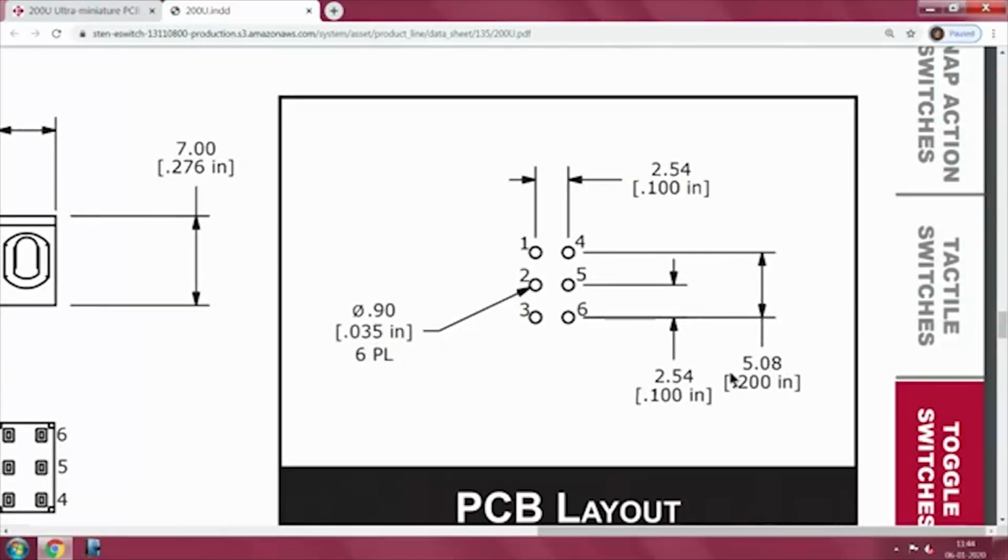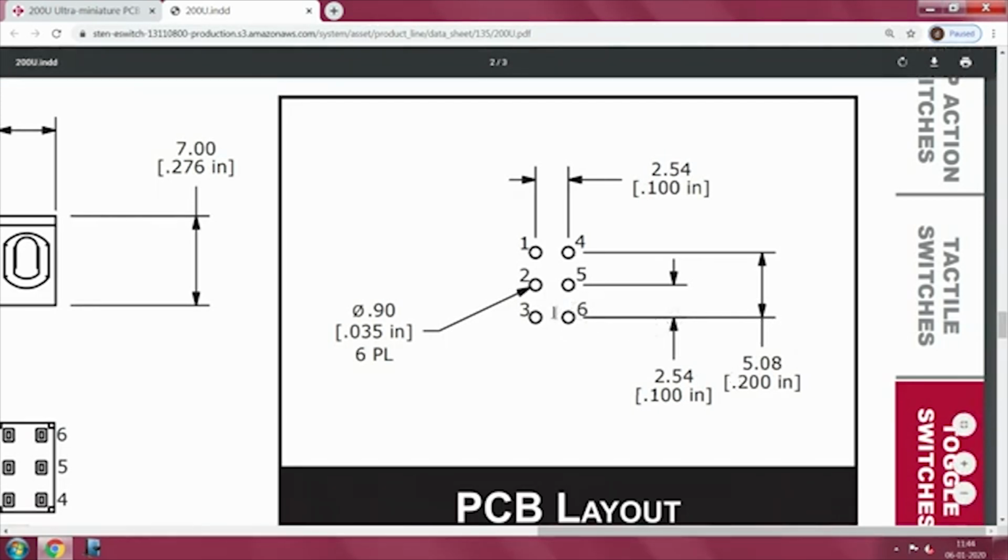So, especially if you are going to have a large number of components and all of them are going to be mounted on a printed wiring board, and that printed wiring board is likely to be laid out automatically, it is much better to look for devices which will give you this 0.1 inch which is given here. That is the reason why in spite of this thing I keep showing you this. You have seen this? Is a beautiful 2.54, and similarly this is 0.2 inches.